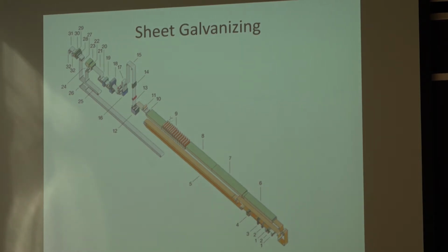That was really key in the automotive industry for them starting to use it. The other aspect is that it's at the detriment of how useful that galvanizing is, because about half of it you lose in the process. Half of the protective aspect of the zinc that you put on, you lose by creating that roughness from the heat treatment. Thank you.